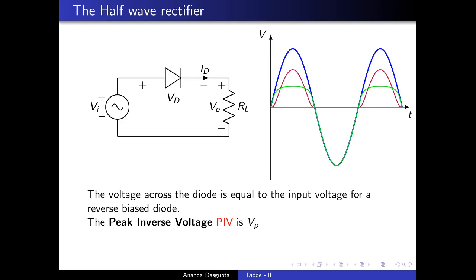Once the voltage exceeds the threshold value, the so-called peak inverse voltage, the diode starts to conduct, and in fact it conducts very heavily and produces a lot of heat as a result. Unless the diode has been specially designed to withstand such heat production, it would be disastrous for the diode. You would end up with a burnt diode in your hands.